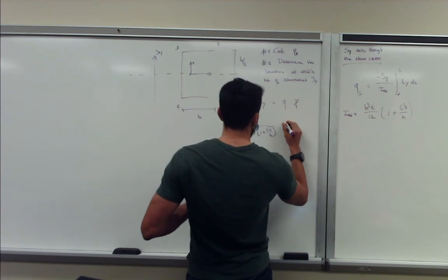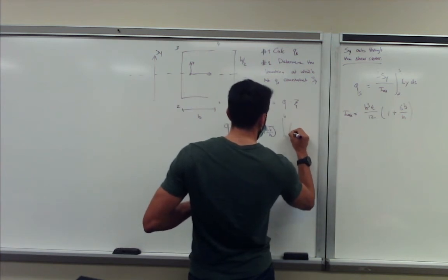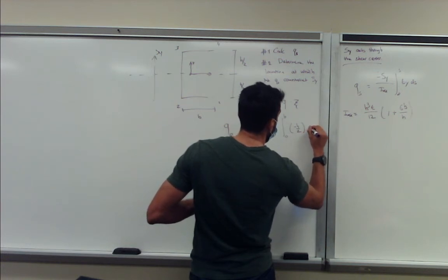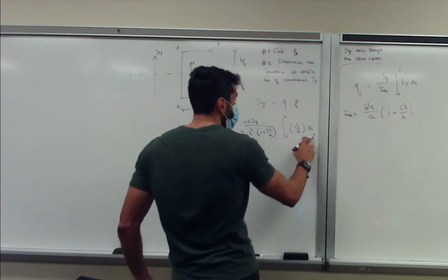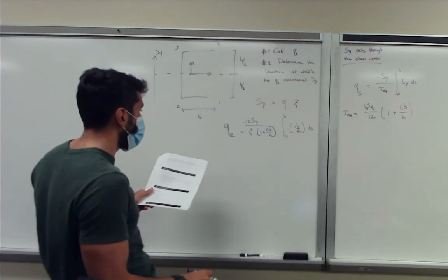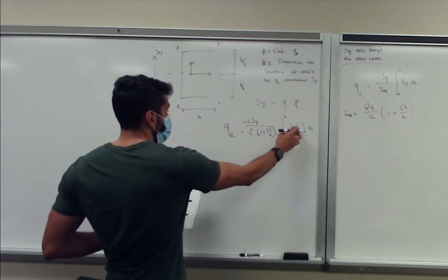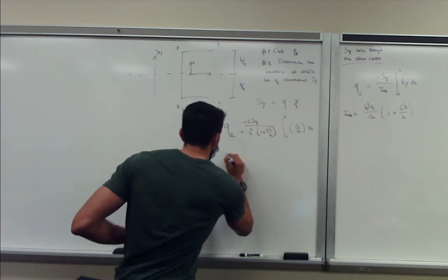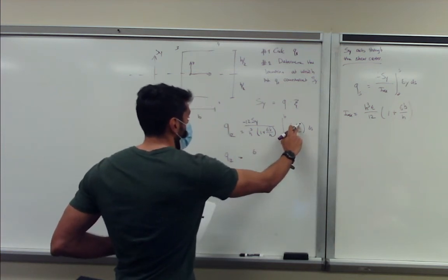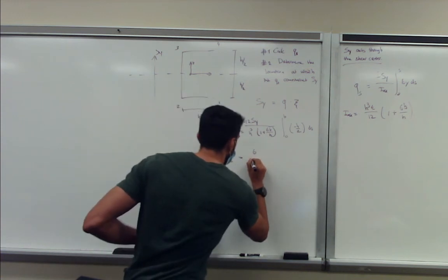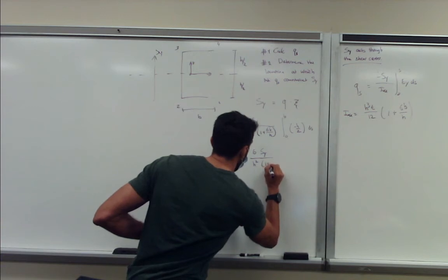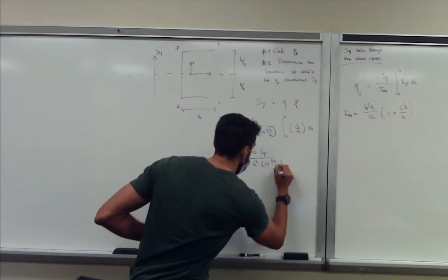Then we have the integral from 0 to b of negative h over 2 ds. If you multiply this out, the negative h, so Q12 becomes 6 because there's a 2 here, 1 h drops, the negative drops. So we get 6 Sy over h squared times (1 plus 6b over h).